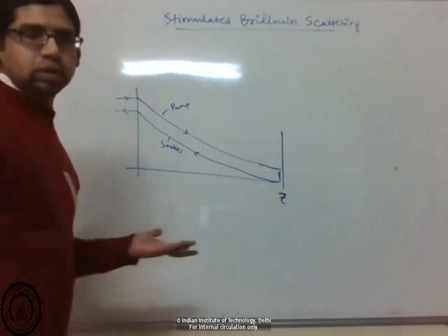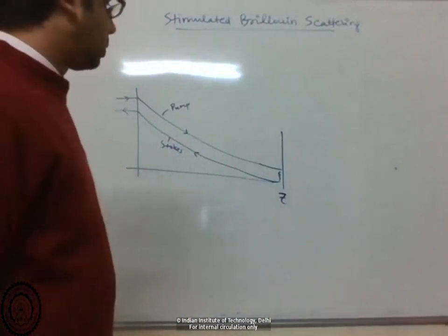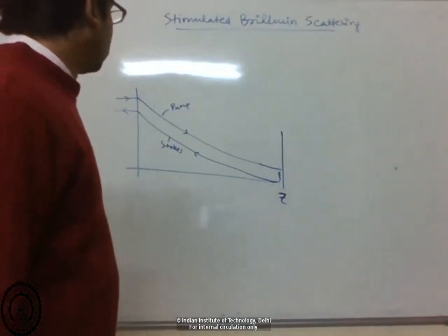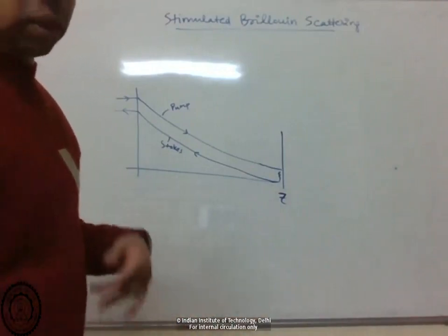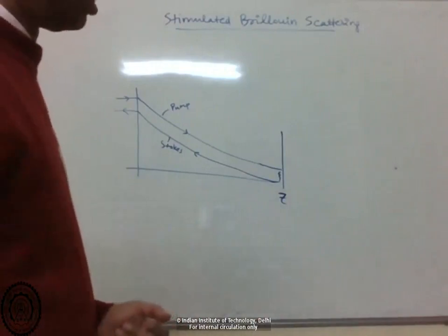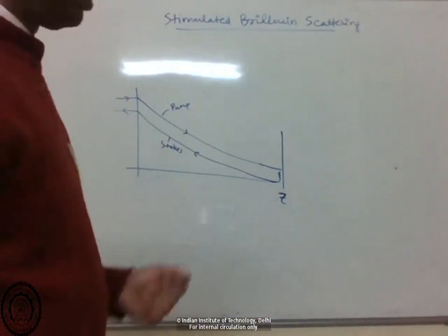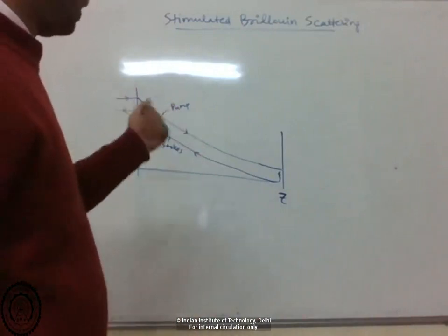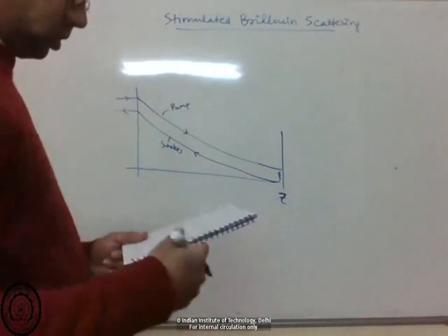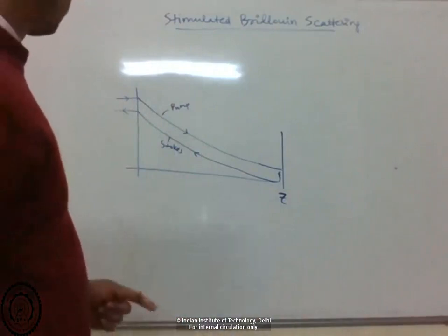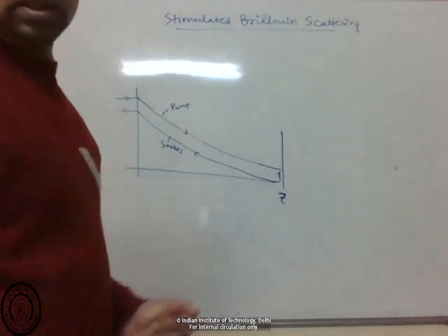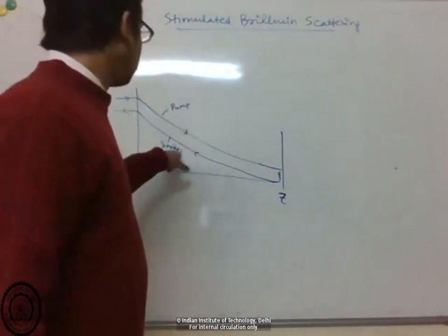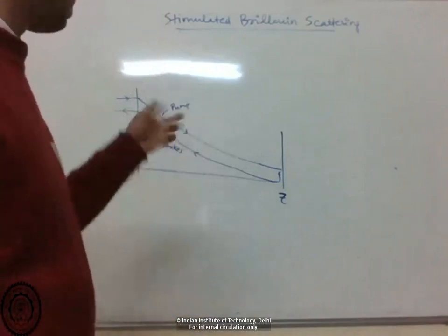So this was a huge problem for optical fiber communications in the beginning. But it turns out that as we've been going to higher and higher data rates, that actually helps in reducing this SBS backscattering. This analysis that we did was for monochromatic waves, so the pump was at a particular frequency and it scattered into the Stokes at one particular frequency, downshifted by the Brillouin shift.